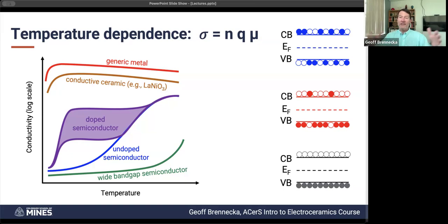That means the surface can stay just below the melting point and stay solid, and inside you can have a little bit higher heat within the center, and that stays molten. That way you don't have to have a crucible that can contain the zirconia, because having something that holds molten zirconia at 2400 C or so is not an easy thing to do. But you have to get the center of it hot enough somehow in the first place.